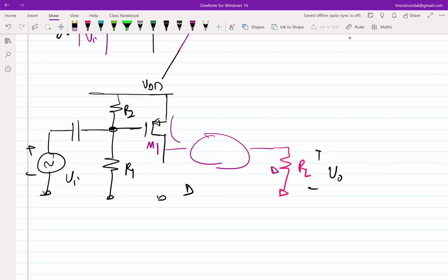Okay. So let me get rid of RD for the time being, then we'll see. If we don't have RD and we want to get a voltage across RL, is it possible to get it? No, right? Because ultimately, whatever current comes through the device M1 will always prefer going into the short. So which means that I have to put something there. And the most convenient thing to put is some resistor RD, because you already know that works.